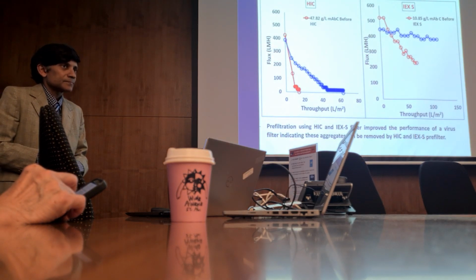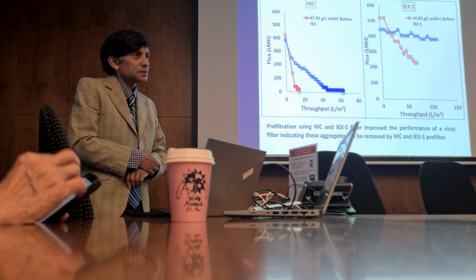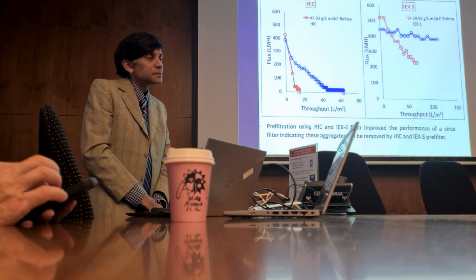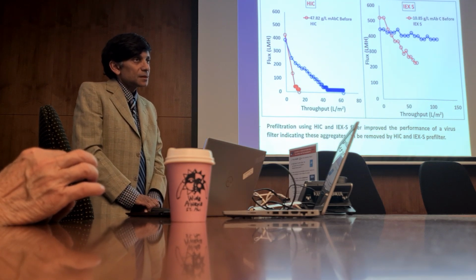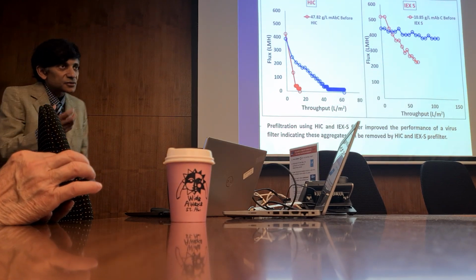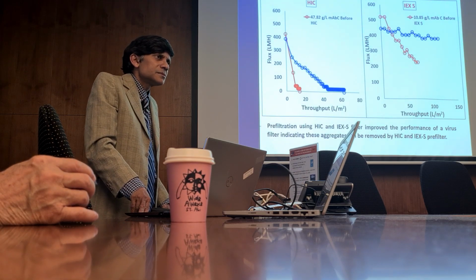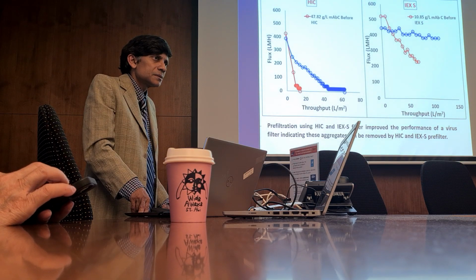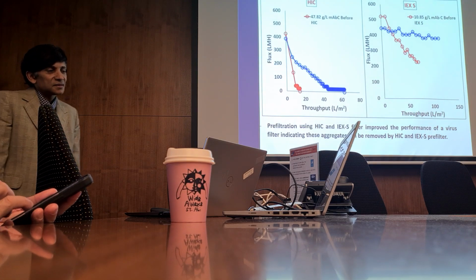So yes. May I have just a short one? What about if we try to immobilize zwitterionic molecules on the membrane? Do you think, based on the hydration bound layer, it can decrease the shear rate or not? Decrease shear rate, I'm not sure. You can certainly try to decrease fouling, right? If you're trying to increase hydration there. How does it decrease shear rate? I'm not quite sure. When you immobilize ions, the bound water layer thickness increases. Then viruses can go through on a pillow of water.